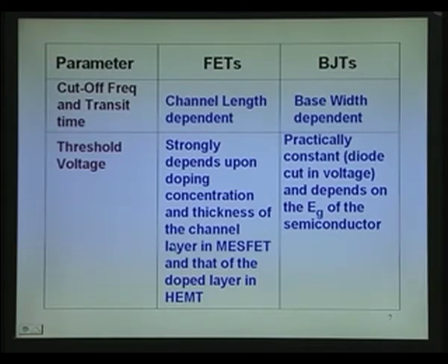Most important of all, okay, the most important of all is the threshold voltage. If you see the threshold voltage of FETs, strongly depends upon what? In the case of MESFET, thickness of that layer, doping of that layer. Threshold voltage depends on VBI minus VP0. VP0 depends upon doping and thickness.